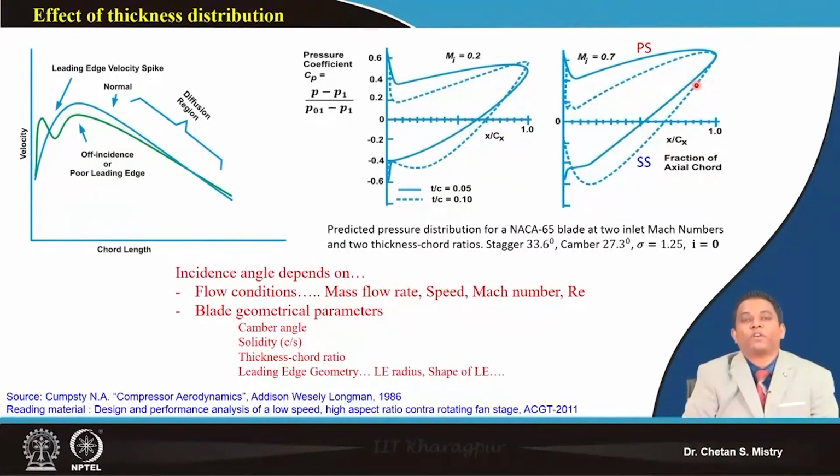For leading edge, the radius is roughly 15 to 20% of my thickness ratio, and for trailing edge, approximately 0.5 to 0.7 of my thickness ratio.